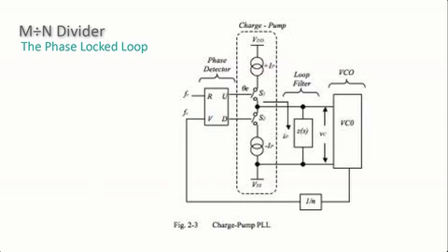Well, here's another phase detector that uses current sources to charge and discharge the capacitor in the loop filter. In the phase detector block, the reference frequency is applied to the R input, and the output of the VCO, divided as appropriate, is applied to the V input. The U and D outputs drive the frequency of the VCO up and down, respectively.